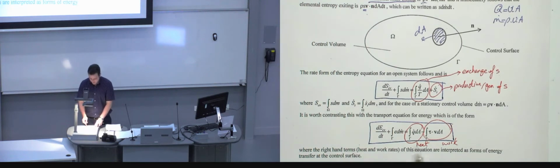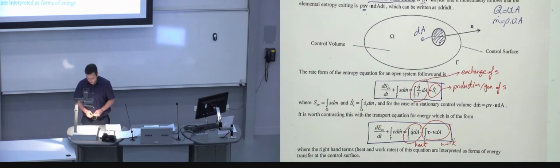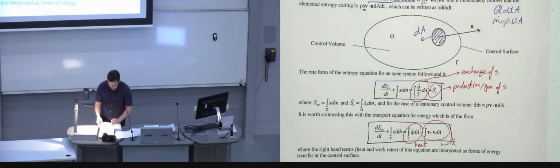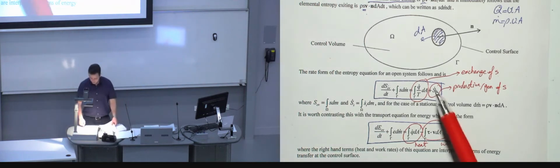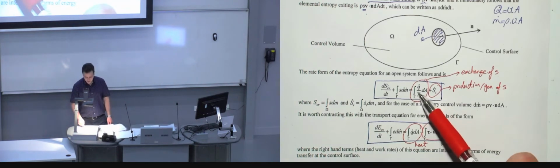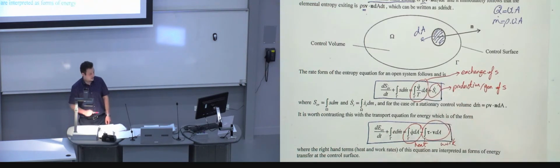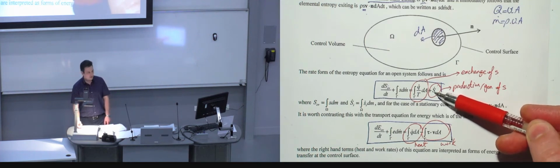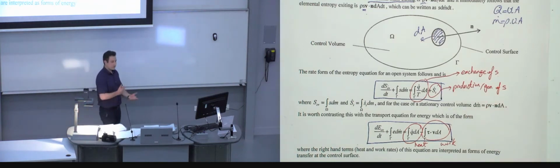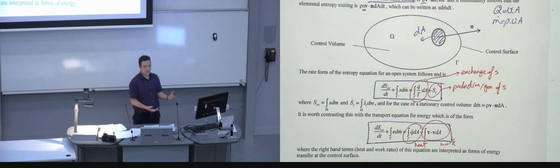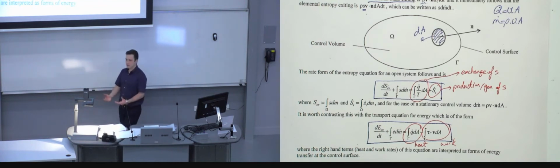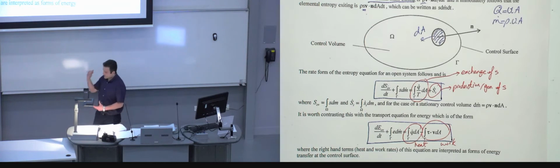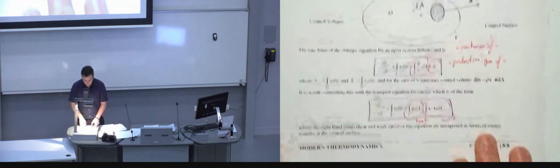So, in other words, on the right-hand side of this equation, you had two forms of energy transfer, heat and work. Now, the question is, it seems when it comes to entropy, we still have something related to the heat, because you still can see the Q there. But then that term certainly doesn't have any resemblance to work. So it seems, even though so far we've been saying that these are quite similar, when it comes to entropy, what happened to the work? We don't seem to have any work term in the unsteady equation for the entropy. And I'm going to explain why that's the case.